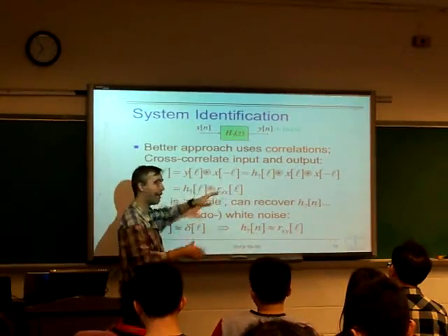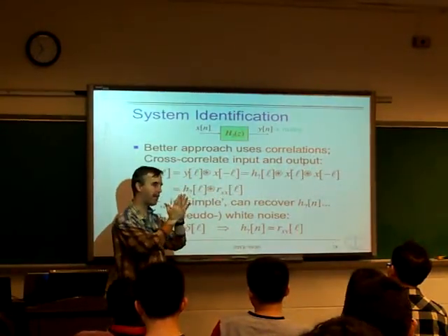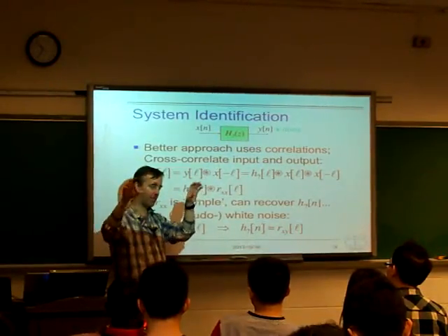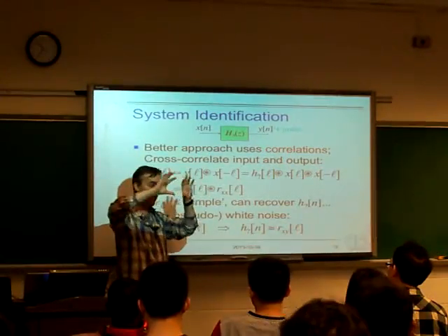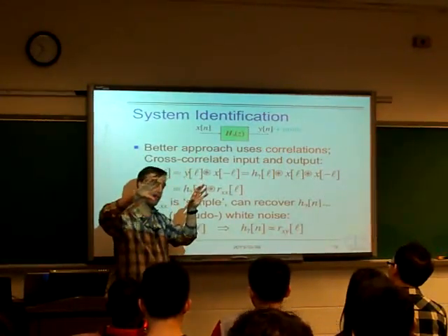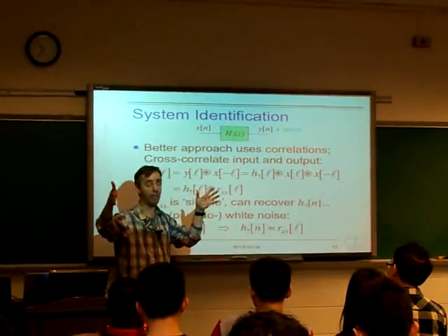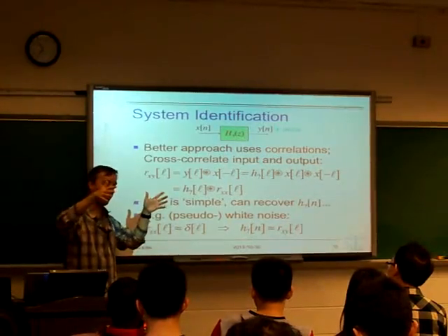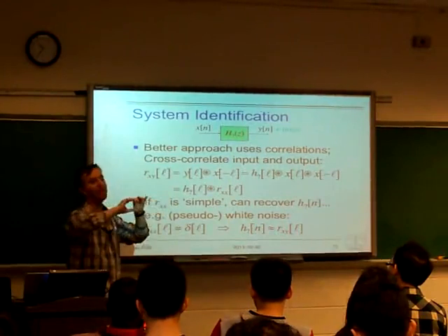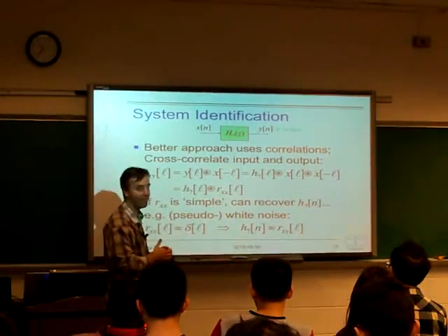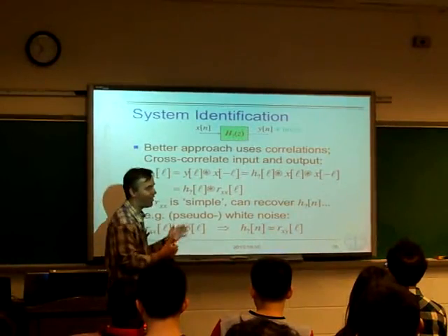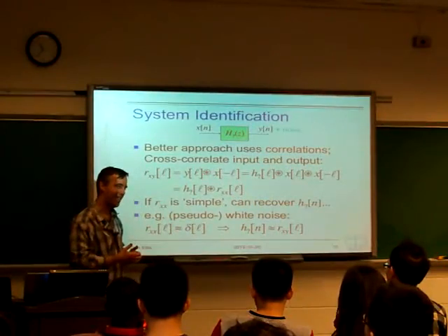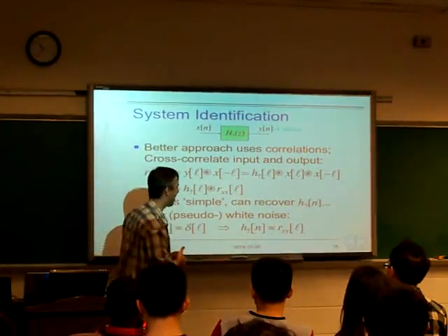If we just want to carry out the correlation for one lag, it's just the inner product between y and x shifted by 1 point, for as long as the sequences we want. So the number of lags we calculate for our cross correlation is independent of how long a sample of the two signals we use. But the longer the sample is, the more accurately we're going to measure those two, because the noise will wash out, basically. If you take random signals and noise, which is often next semester, you'll deal with this stuff much more rigorously.